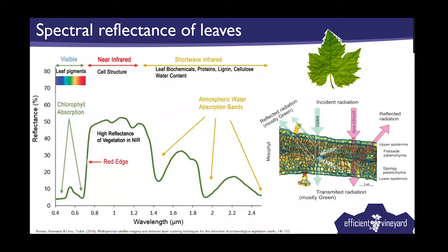And I will just mention briefly, because it is used in some of the vegetative indices, and we'll discuss what those are as well, that red edge. The red edge is the transition between the visible and the near infrared spectrum. So as you're measuring reflectance in wavelengths moving from red to near infrared, you're going to see this really marked spike or boundary in reflectance. So that's what they term the red edge.